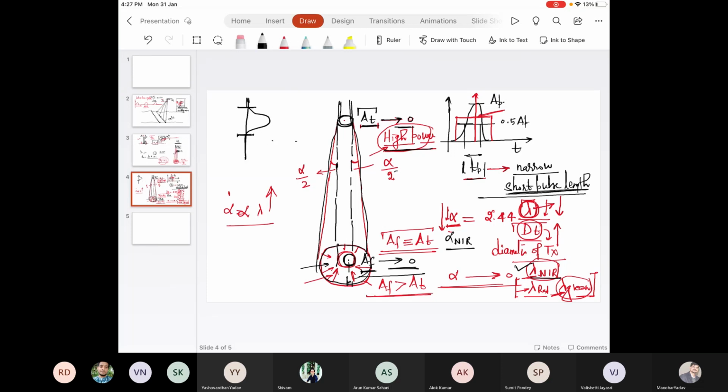Let's say this is time T1, and this is T2. This distance is called the pulse length. Generally, we define a 50% level, TP. So TP multiplied by C, if it is an air medium, is called the length of this pulse in the air when it travels towards the target.